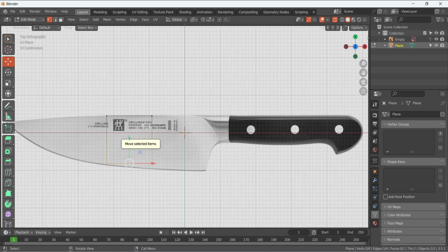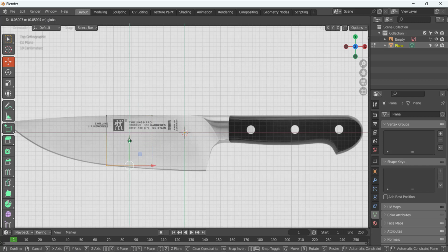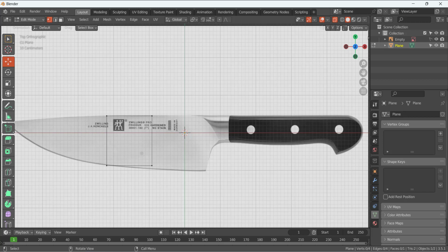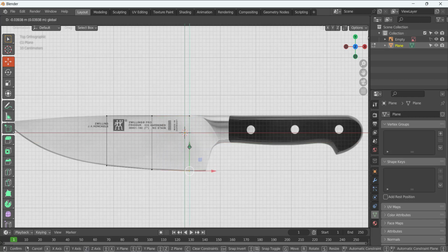And for these two I'm going to move them, so just drag the shape of this blade. So we have here a blade and a handle and some pins to assemble them. Okay, so for now, for this one I am going to make it below, move it in the Z direction. So you just drag the outer edges of this blade. I'm going to select it, press E to extrude it, and make sure you lock the X-axis so it's moving in the X-axis direction, and just place it here.